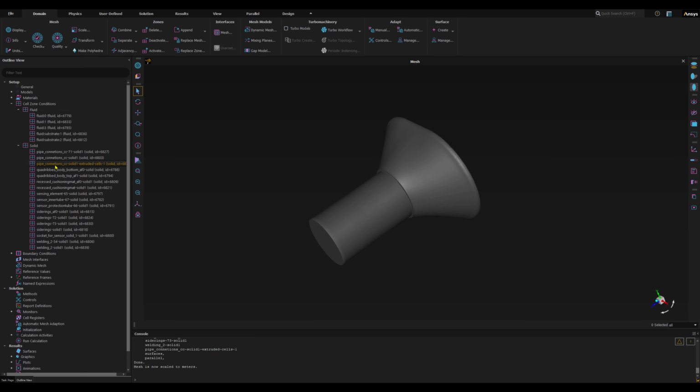But for the solid part, as you can see, we have added this area that was newly created here. If I right click here and add to active window, you will see we have two separate solid parts for this pipe region surrounding the inlet, but this fluid, as you can see, is just one region that we have extruded recently in Fluent Meshing.